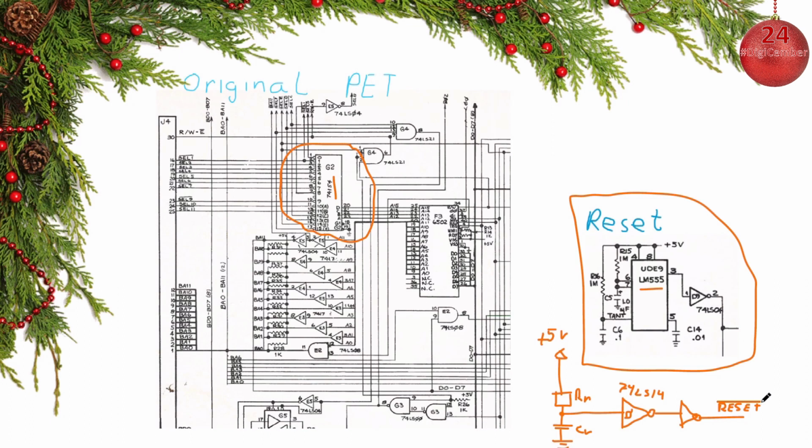This is reset low, and we also have, if we want, the reset not inverted here, if we ever need that. And this trickery here will make this a more sturdy circuit, because as we remember, this has a curve like so, and this V low state here is somewhat undefined, so it can vary a bit. But with this, it will be a more predetermined state.